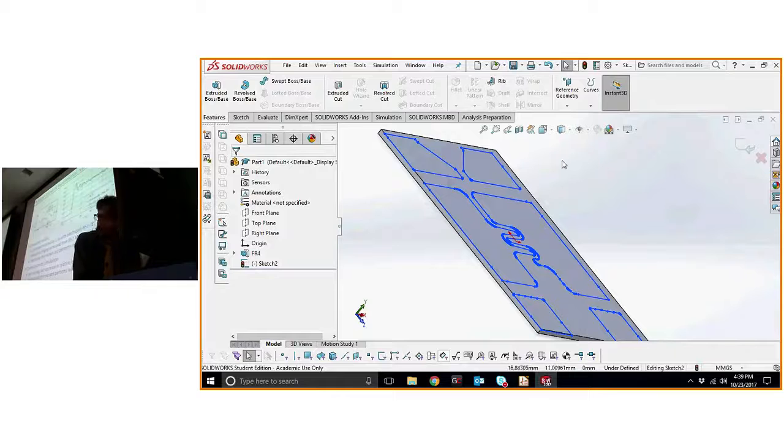Yes? You said select the top plane and not the top board? Yes. It's because whenever you put the bottom plane in, if you selected the bottom part of the board, it's how it treats the normal vector. So it won't mirror it like you would. It's not like you're looking straight through the PCB. That's how it exports it. You could probably export it mirrored and it would work, but I just refer everything to that same plane.